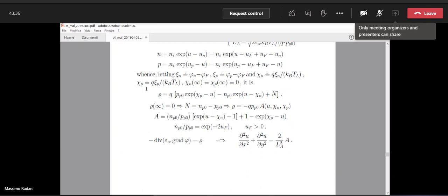When we consider the Poisson equation in the MOS capacitor, we solve it for any value of the applied voltage, okay? So the solution of the Poisson equation in the MOS capacitor is fully general, so it applies in strong inversion, weak inversion, depletion, flat band conditions, and accumulation.